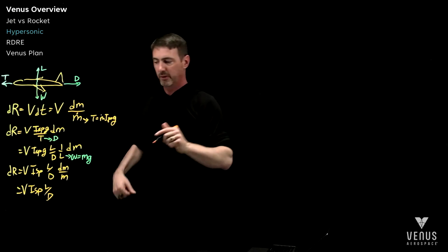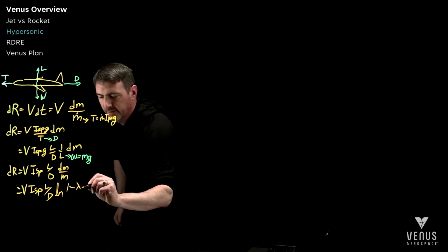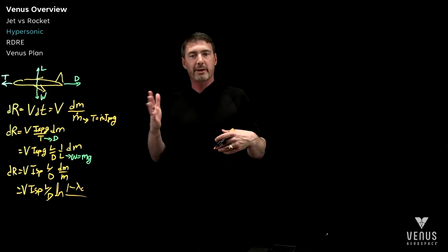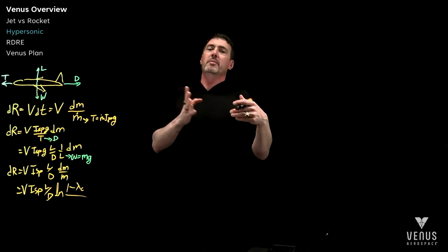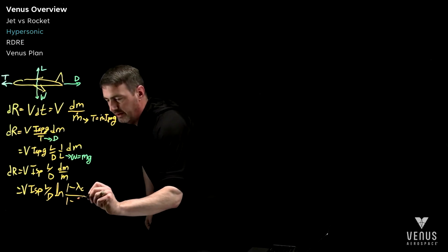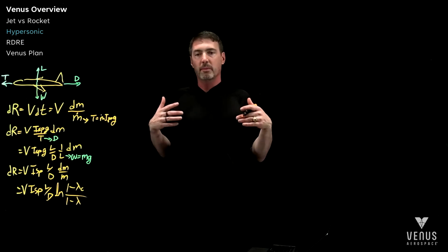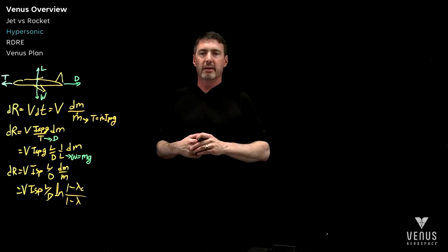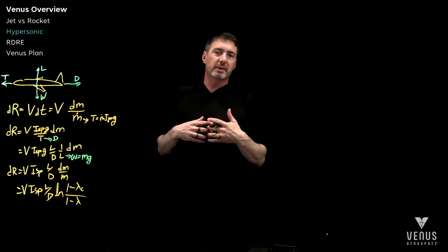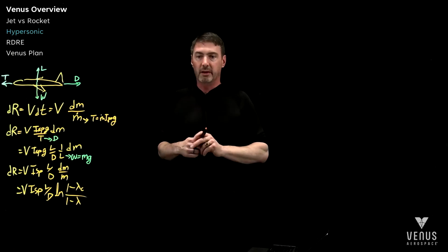I'm going to convert that into the other form we were using. And so the initial is how much propellant I used to get up to that cruise speed. So one being takeoff weight, 1 minus lambda cruise being how much I used to get to cruise, and then 1 minus lambda total, the total packet of fuel or propellant that is carrying. Now, again, for a purely turbine-based combined cycle, that's only fuel. For rocket-based combined cycle, this would represent both the fuel and the oxidizer, so the total propellant being used.